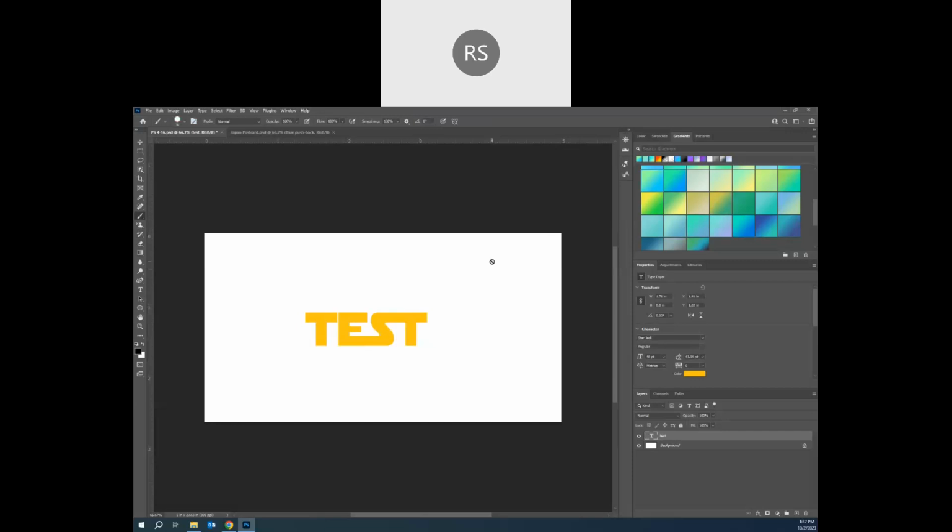Okay, so when I rasterize text, that means I'm converting the type to pixels. Adobe users also refer to this as changing the live type to outlines. So once something's rasterized, these type outlines don't appear to change, but then they can be manipulated like all other Photoshop artwork can, because once they're rasterized, these type outlines are just pixels.